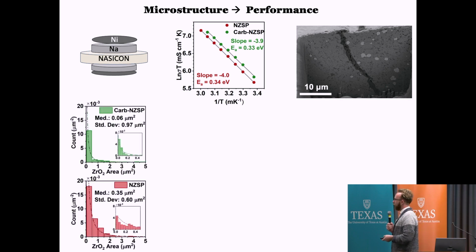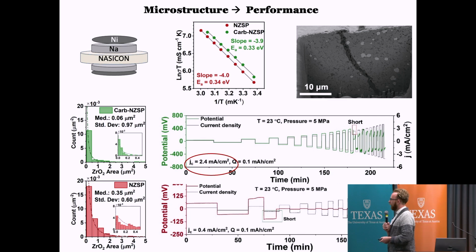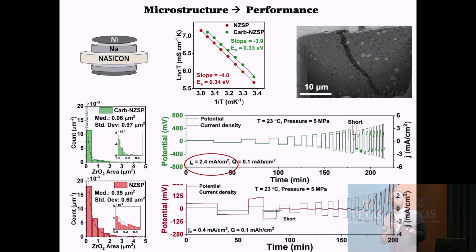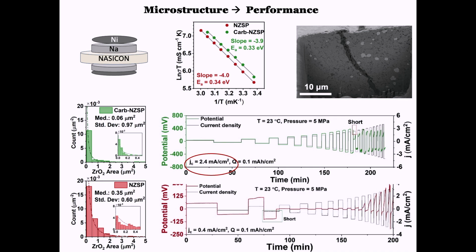So our basic approach is to stress test our cells by progressively increasing the current until we get one of those short circuits to occur. So what we want to do is we want the current to go as high as is conceivable before we get a short circuit so that we know that these batteries are actually safe. What you're looking at here in red is our baseline sample made from essentially an average recipe you would find looking through the history on this material.